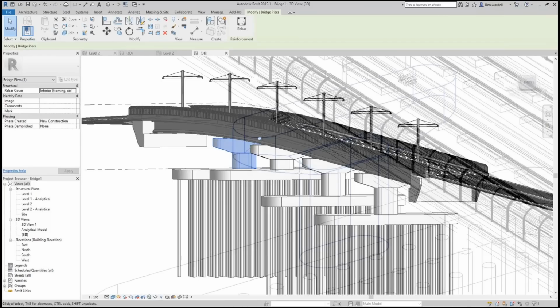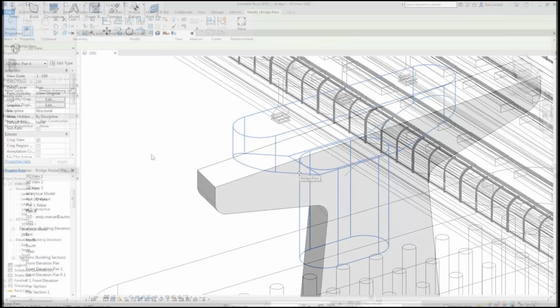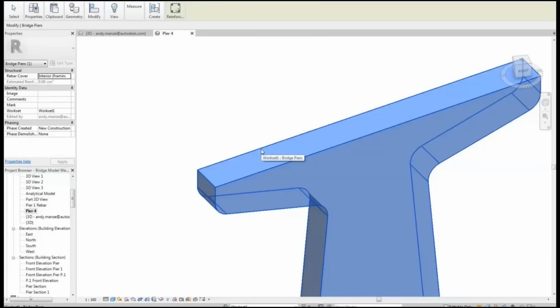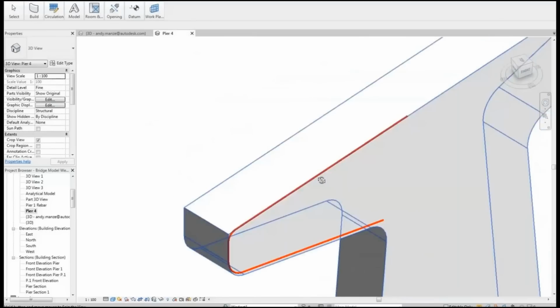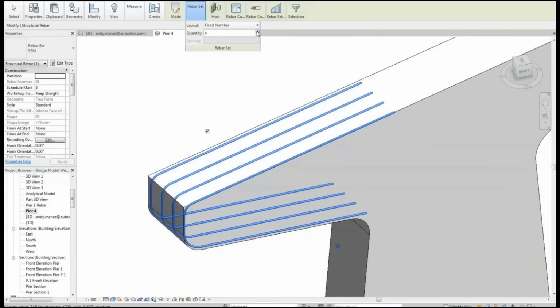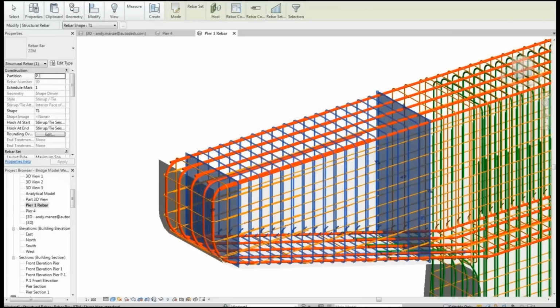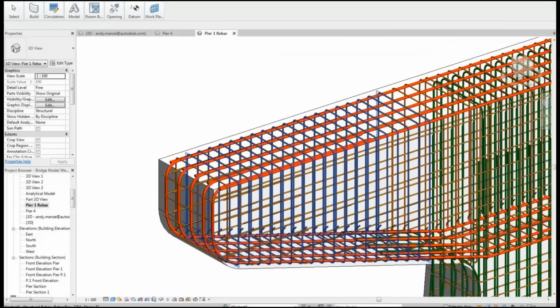And once we've got it in Revit, and this is just showing a simple workflow, we can select that, and this is a slightly different bridge pier, but the concept is the same, where the structural designer can go through and add anything that they need to in regards to their rebar details. And so everything within Revit at this point can be designed right here. We can create cut sheets from here. We can show the full rebar details, quantities, anything we need to at this point.